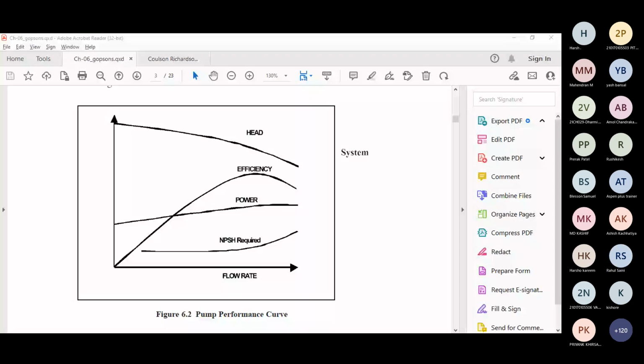And why do we use them for viscous fluids? Because they cannot escape through those gaps, so sealing is proper. Similarly, when we talk about gear pumps, if we pump water through a gear pump, you will not get the flow because the water escapes through the space between the gears. So gear pumps and PD pumps are mostly suitable for viscous fluids, whereas centrifugal pumps are highly suitable for non-viscous as well as cleaner fluids like class A solvents or water.